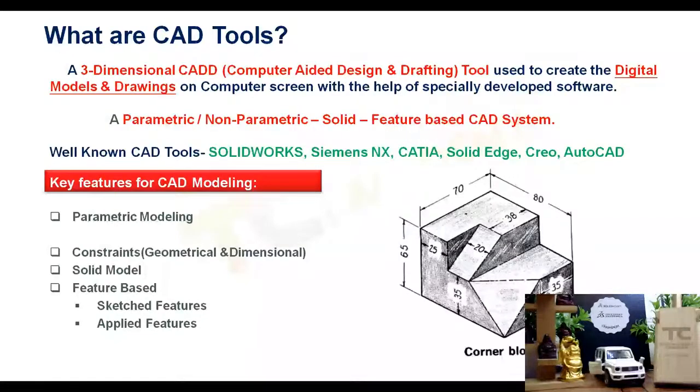If you assign a material for this, automatically the software will take the density into account. So let's say your practical model is weighing 1.5 kg, and if you want to see the same here, what you need to do is assign the material. If you assign it there, the density will be assigned. So that as a reference, it will give you the weight information inside the software.